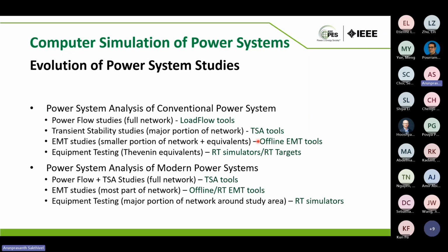And when it comes down to equipment testing, people modeled only a relevant portion of the network, and the remaining was modeled as purely Thevenin equivalents. For that purpose, real-time simulators or real-time targets were used for equipment testing.